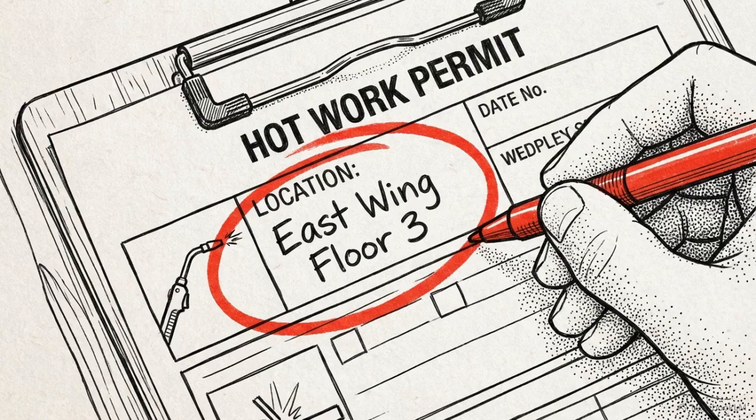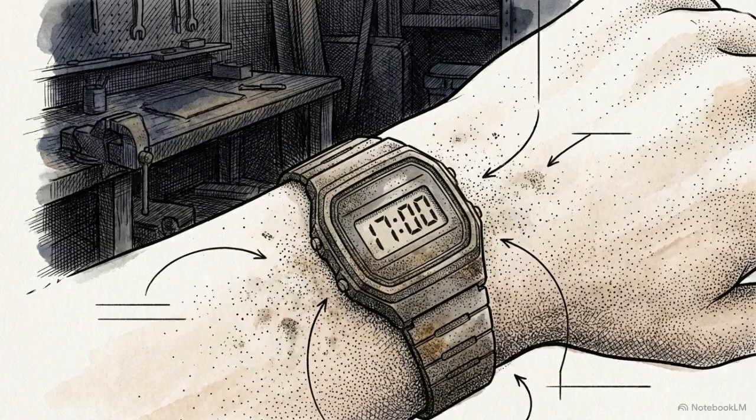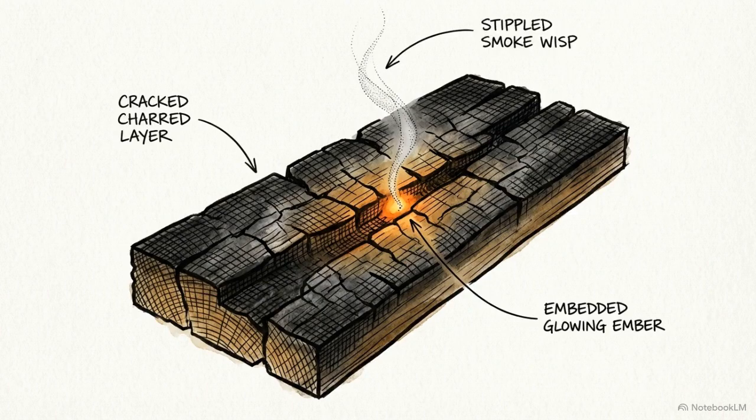A hot work permit enforces mandatory constraints. It must be specific to a single task in a clearly identified area, authorize the presence of appropriate fire extinguishers, and account for any adjacent processes involving flammable liquids or gases. The permit specifies a mandatory final fire check at least 1 hour after the work concludes. This delay is critical to catch slow smoldering caused by conduction or convection heating.